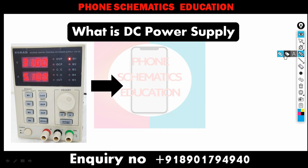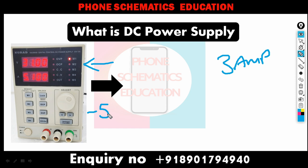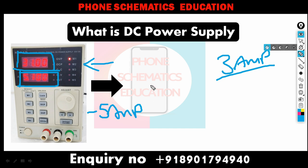But I have one recommendation: use 3 amp and above. I'm using this one, a 31 volt, 5 amp DC power supply. If you use 3 amp minimum, it's good for you. Analog or digital, it doesn't matter.